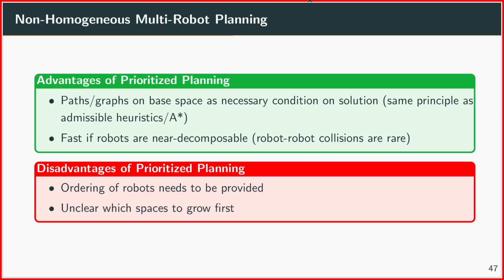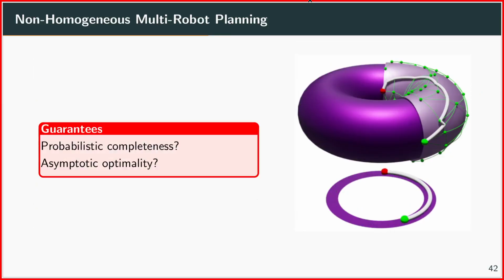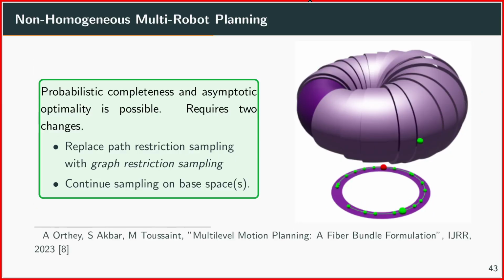Of course, this incurs more cost. If the optimal path for the first priority robot blocks the path for a different robot, then it can't find it. Yeah, that is why in this case you would sample the whole roadmap. You would not only take the optimal path on this roadmap, but you would take any path on this roadmap.